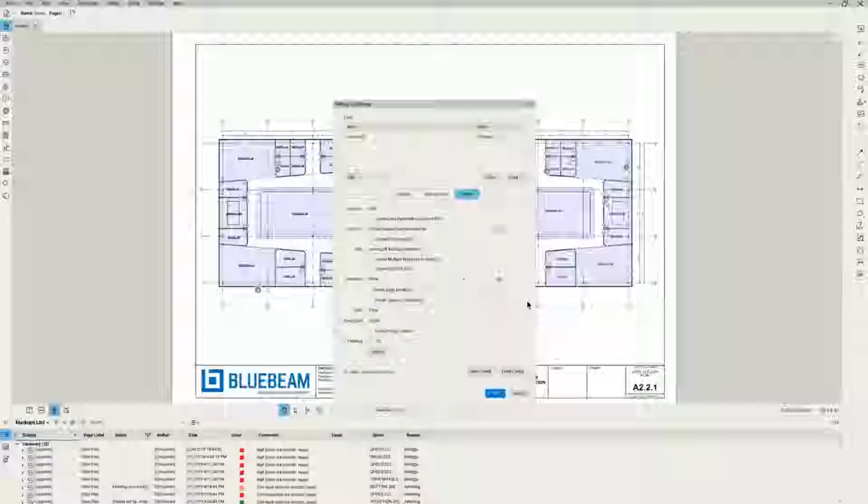I think that's a very important one, and I think it also really emphasizes the importance for those of you that are using Bluebeam CAD or Bluebeam Extreme. It emphasizes the importance of using the Bluebeam plugin versus the Bluebeam PDF driver that can be found under any print menu. So I wanted to address that while David was reopening this PDF.